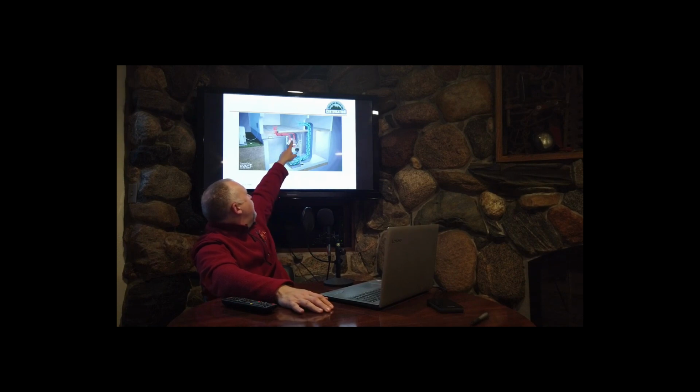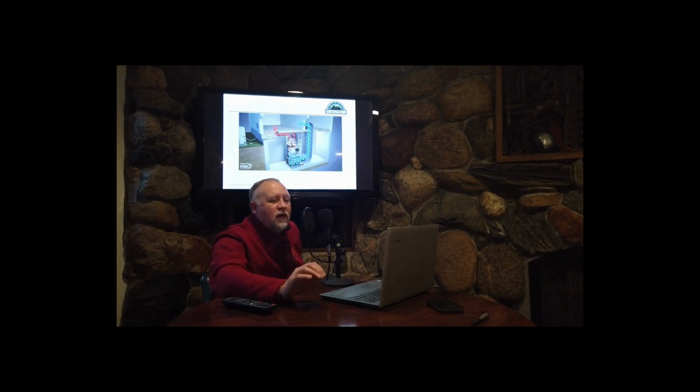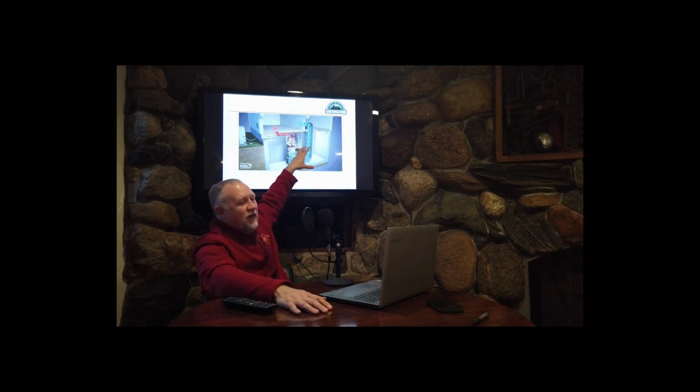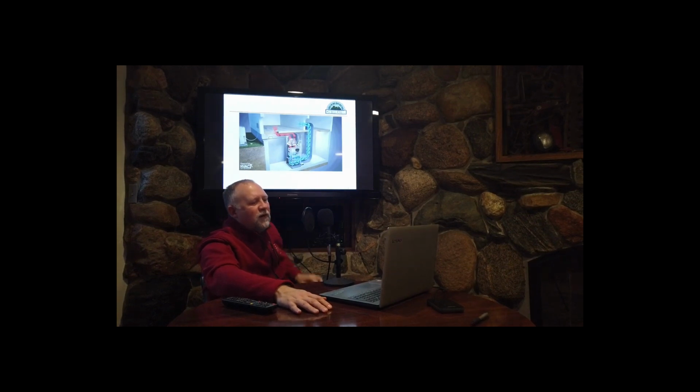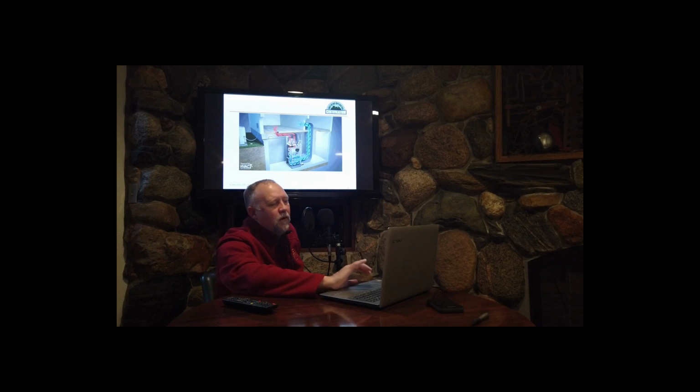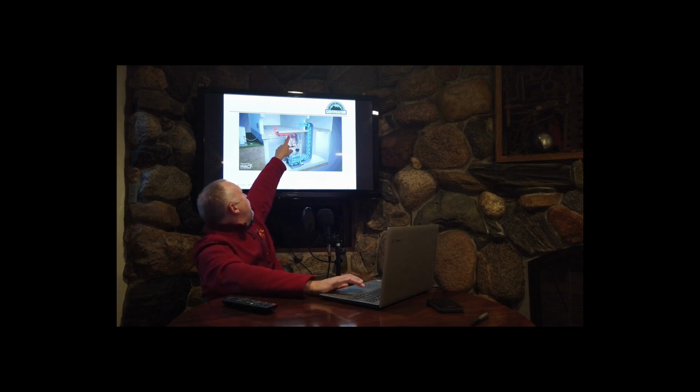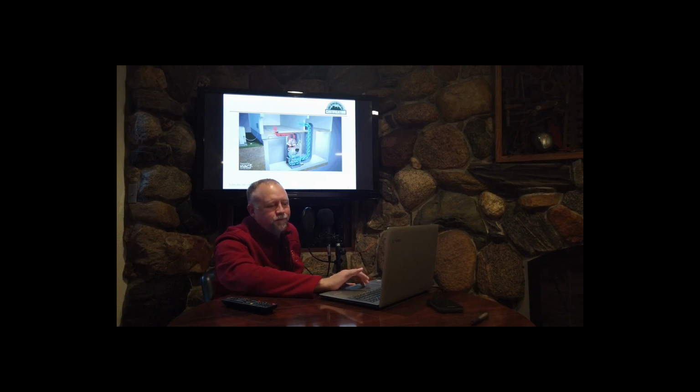It's hot now, but this is the air conditioner, the air conditioning coil that we're going to look at when we talk about air conditioning. Think of this coil as like an accessory that you bolt on to the furnace section. All we're going to do is use the same ductwork and supply fan for the air conditioner that we do for the heater. All right, and then once this air is hot, we blow it through the ductwork into the room, and the process keeps on going.